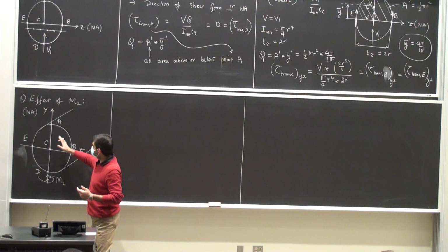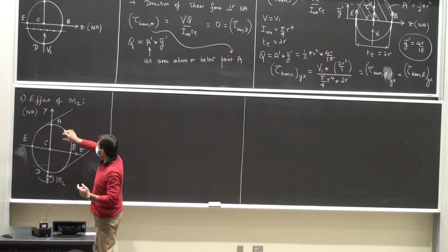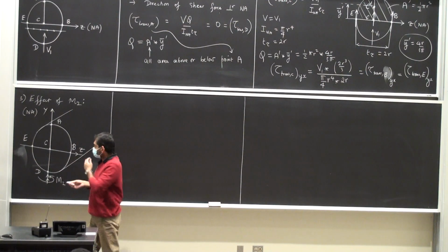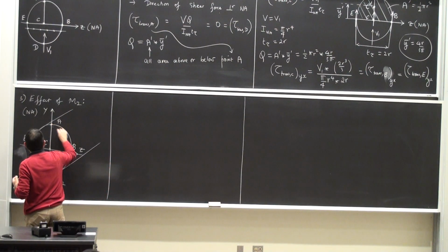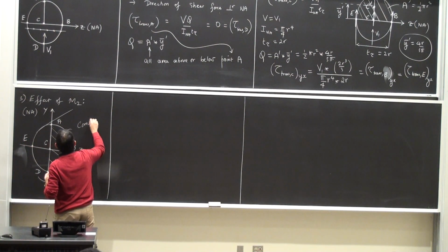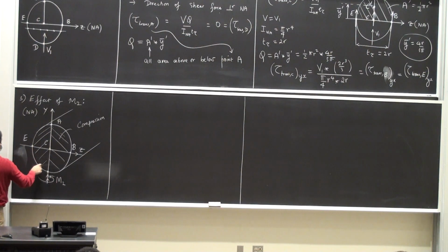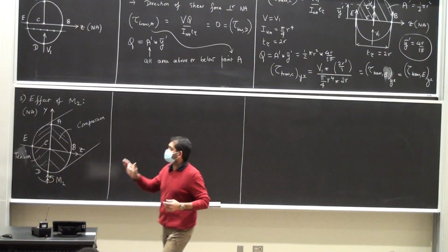Right. So the bending moment is trying to take all these fibers. If you imagine long lines of fibers, they're just getting pushed inside. So this part is going to be in compression. All of this. All of these, tension. And while I'm at it, let me also draw the other cross section.